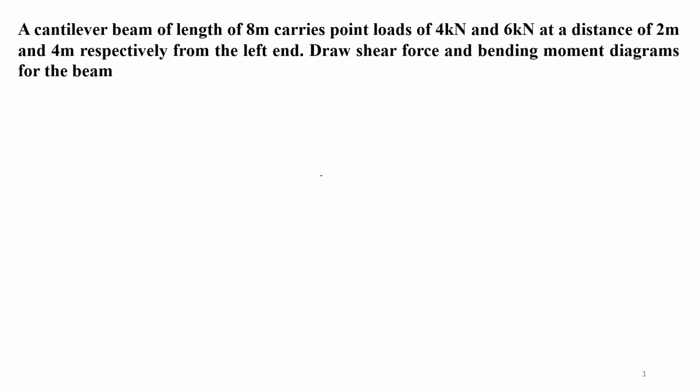Hello all, so in this video we will solve a problem related to shear force and bending moment for a cantilever beam. So here the question is given as a cantilever beam of length 8 meters carries 2 point loads of 4 kN and 6 kN which are at a distance of 2 meters and 4 meters from the left end respectively. So first of all let's try to draw the cantilever beam.